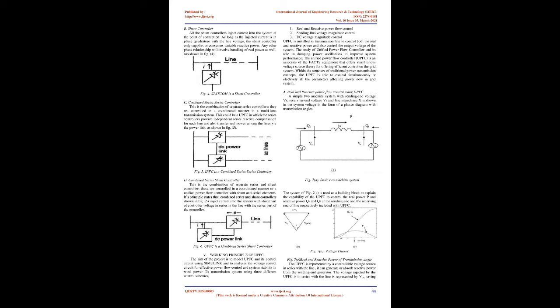The term weak grid is generally taken to mean that the voltage level is not as constant as in a stiff grid. Weak grids are generally found in remote places where the feeders are long and operated at a medium voltage level. The grids in these places are generally designed for relatively small loads. When the designed load is exceeded, the voltage will be below the allowed minimum level and the thermal capacity of the grid will be exceeded.